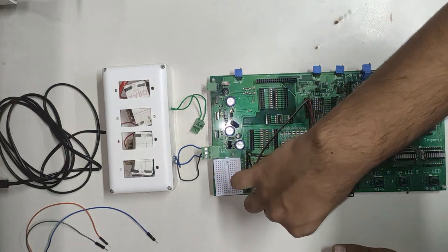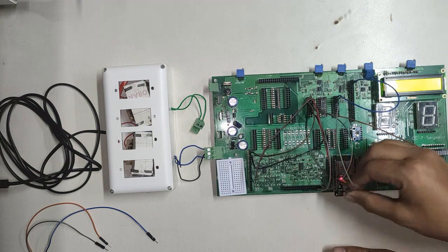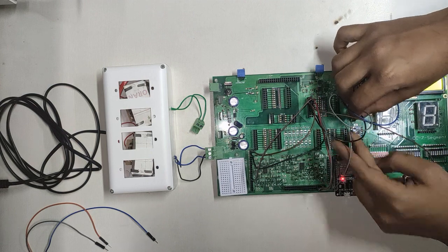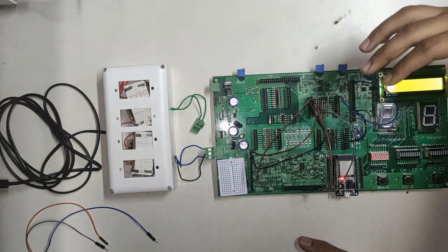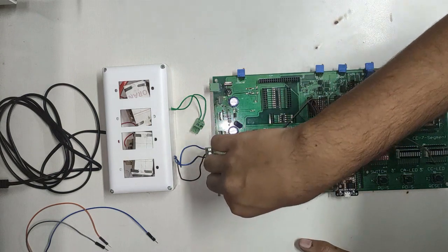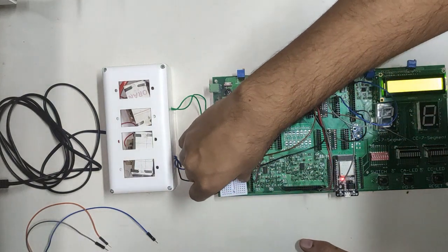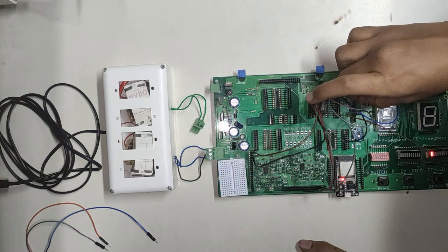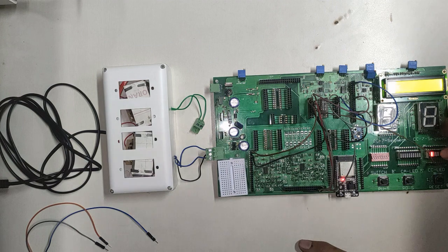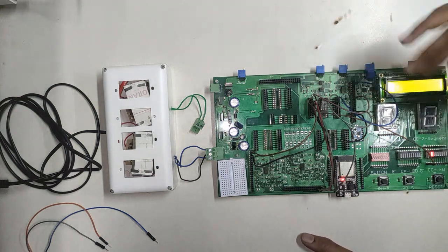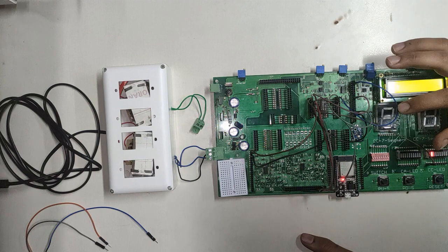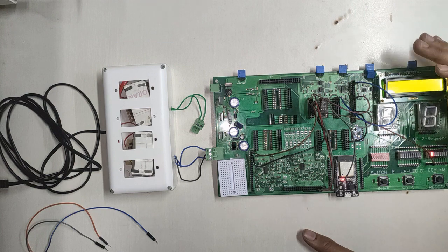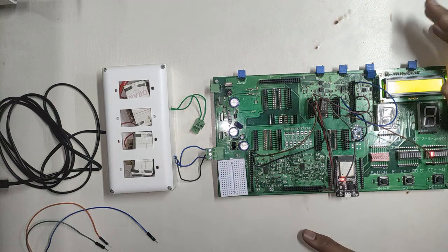If we change the case, here I am making both the values of S0 and S1 plus 1. The binary equivalent of 1 1 is 3, so the output of the mux will be D3. Here we can see that when D3 is 0, the output is 0. When D3 is considered as plus 5 volt or logic 1, the output is logic 1. So the output of the mux in this case is nothing but D3. Similarly, by varying the values of S0 and S1, we can get the other outputs, which are D1 and D2. That's it.